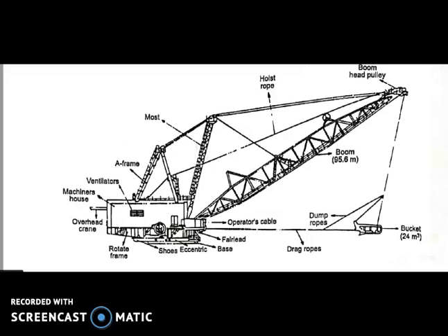The motor generator, the MG set, is placed at the rear part of the machine. It consists of an AC synchronous motor and exciter, a hoist generator, a drag generator, and a swing generator. The hoist system occupies a space in front of the MG set. The drag system is placed in front of the hoist system, while the working system is positioned in front